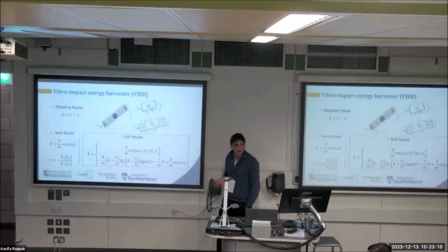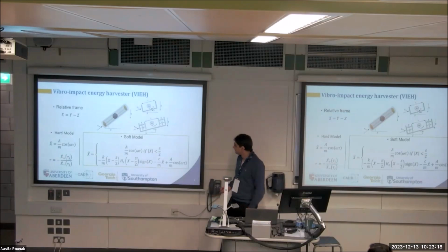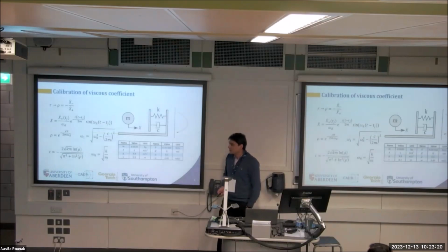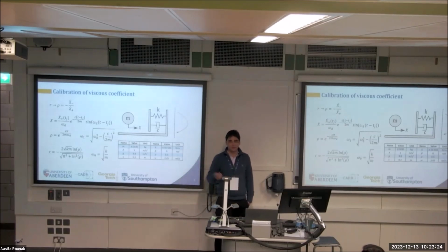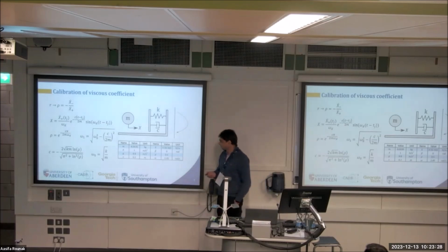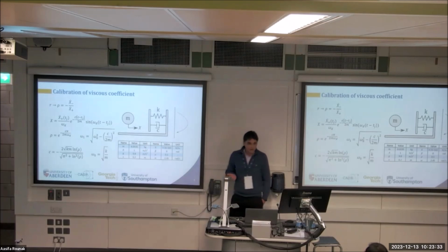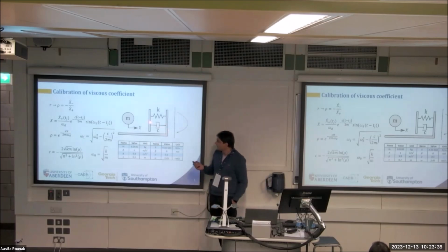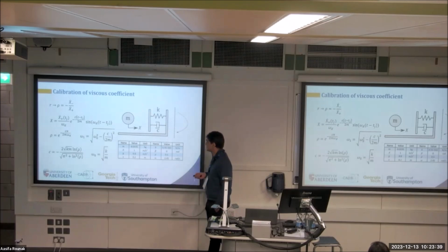However, if you saw our experiments, we measured or fixed the coefficient R here. So we actually need some form of calibration between a hard and soft impact model. Stiffness we can vary, that is fine. However, the damping coefficient becomes critical when you are dealing with restitution coefficients.